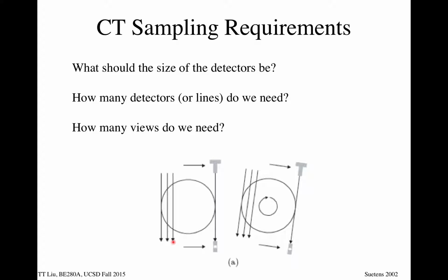All right, it's going to roll it off, right? Because as the rect gets wider, the Fourier transform of that thing gets narrower and narrower. So higher frequencies get attenuated. Okay, so just to first order on a one-dimensional function. Now we saw in CT, because we're doing these polar projections, it doesn't actually work out that way when you're doing back projection imaging. But in a one-dimensional case, if all we were doing is a one-dimensional function, that's a simple way to think about it: a wider rectangle function gives you a narrower bandwidth in Fourier space in 1D, right?